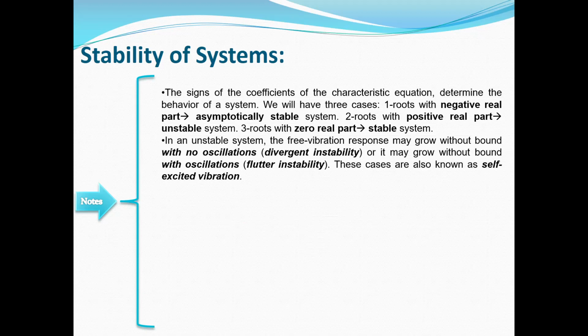Due to the physical behavior and some other reasons, the response depends on the velocity of the motion, but this effect appears with a negative sign, and that negative sign acts as a new term which, instead of decreasing the amplitude of the response, will increase it. It's called self-excited vibration.